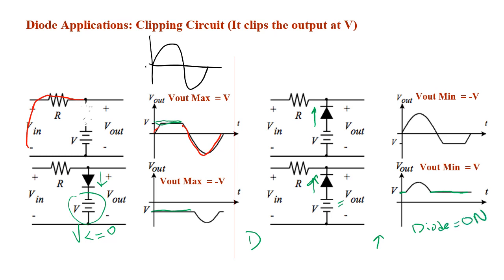You can also say that the diode is on or off. So on means forward biased, or the voltage across it is greater than or equal to VD. When we say the diode is off, it means that the diode doesn't conduct current, or alternatively, it also means that the diode is reverse biased, or the voltage across it is less than VD.